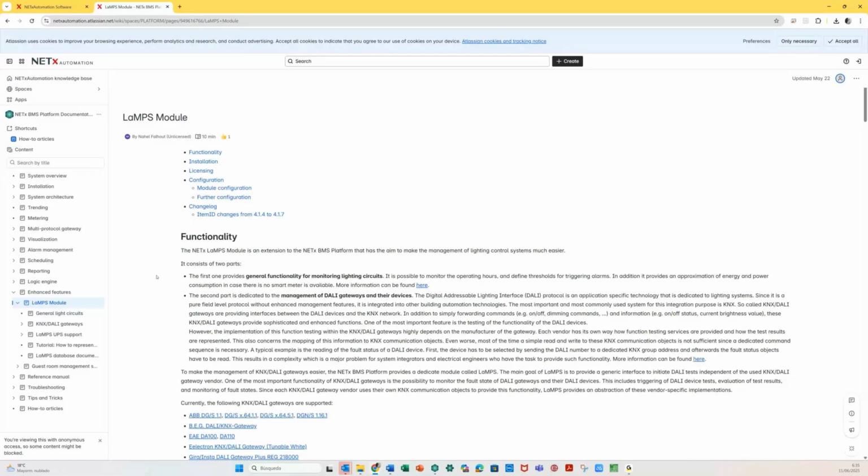But there is a second approach about DALI 2. DALI 2 is a new standard that can also integrate sensors and push buttons in the DALI world. Normally, in our projects, we don't consider using these elements, because KNX detectors and KNX push buttons are much more flexible to integrate.